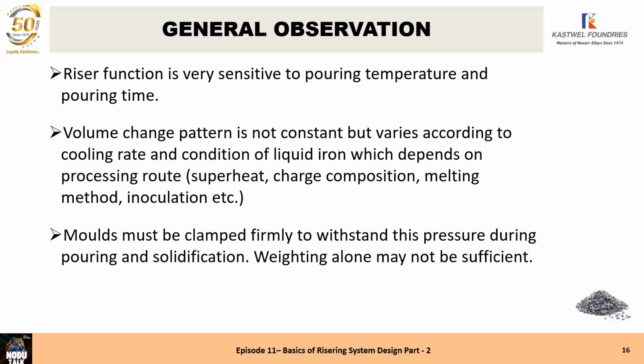So now this brings into the limelight all the important parameters that we consider during the processing of SGI. So riser functioning is very sensitive to pouring temperature and pouring time. The volume change pattern is not constant, but varies according to the cooling rate and condition of the liquid metal, which depends on the processing route. For example, the superheat or the charge composition and melting method, inoculation, etc. These and other parameters affect the volume change.